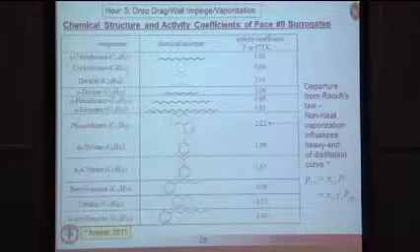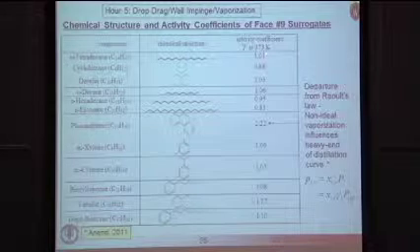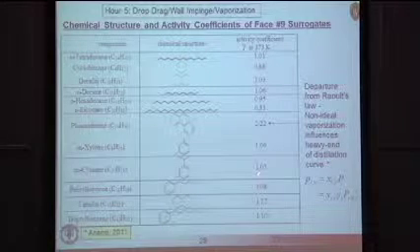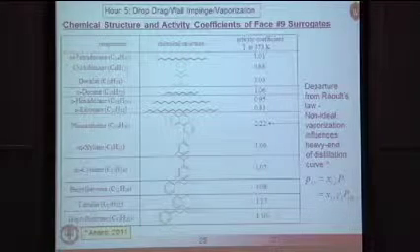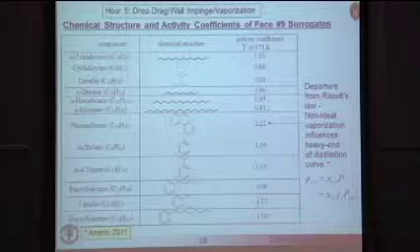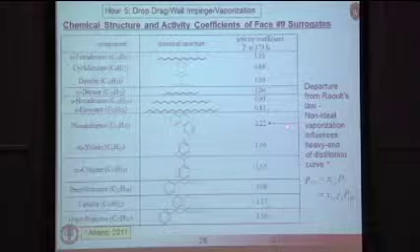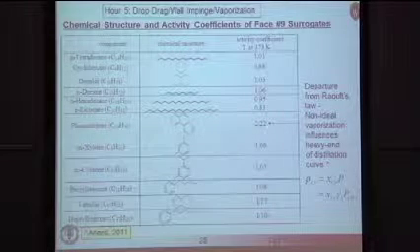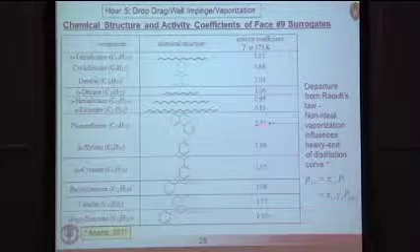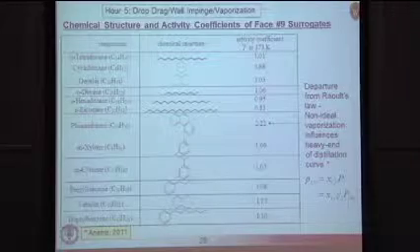There are pictures of those molecules. Interestingly, here are those activity coefficients that I spoke about, the ones that measure the departure from Raoult's law using the UNIFAC method. And you can see that for some of these components, there's a significant impact. Essentially, we're changing the vapor pressure by a factor of 2 for this particular molecule.